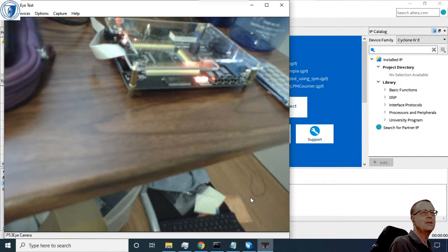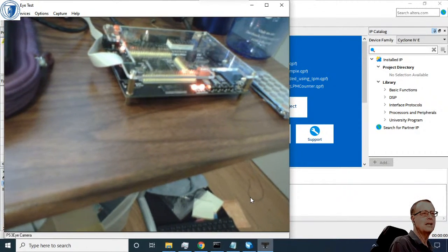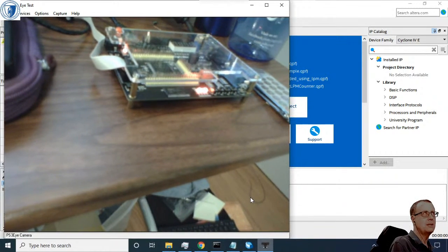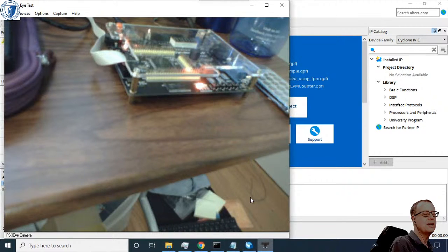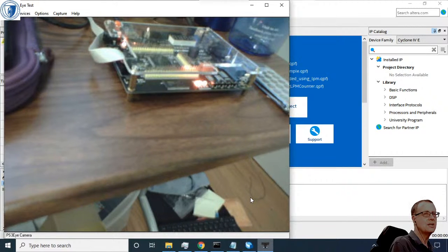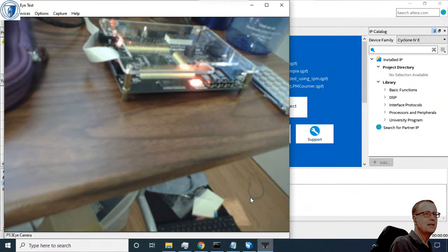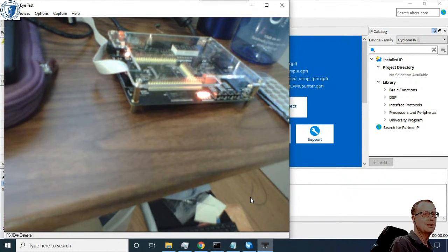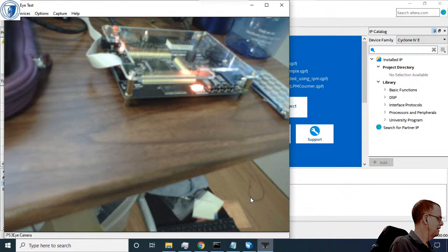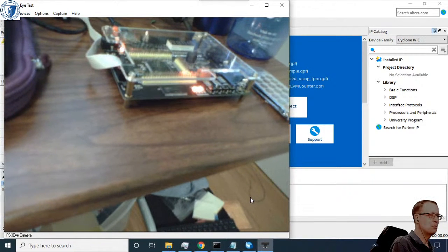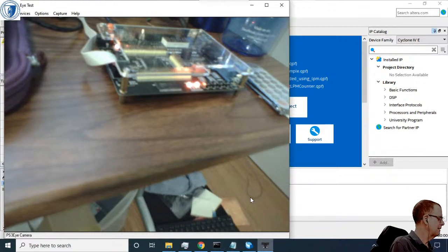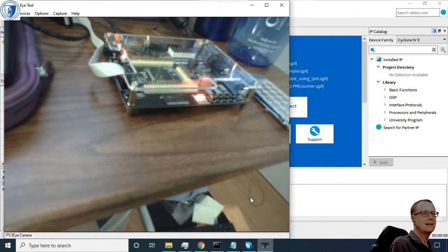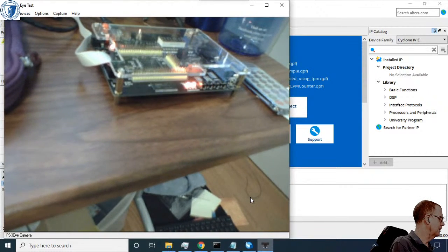But then after the video I added 3 more pins, pulling out bits 24, 23 and 22. So the second LED from the left hand end is now blinking at a 2 Hertz rate. The third LED is blinking at a 4 Hertz rate, and the fourth LED is blinking at an 8 Hertz rate, which is kind of cute.